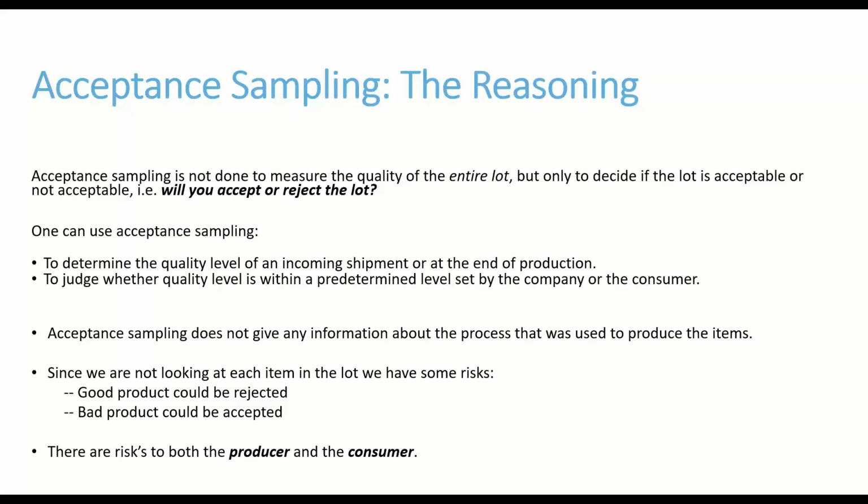However, random sampling is a big deal. If we choose randomly from the lot, don't choose the first 10 or 20 things in the lot, right? Because maybe coming off the line, something happened there. If we randomly sample, then it's going to help us control for any kind of variability that's in the product. And there's always variability. We don't have 1,000 of the same thing exactly the same. There's going to be little variability, but that random sampling will help.